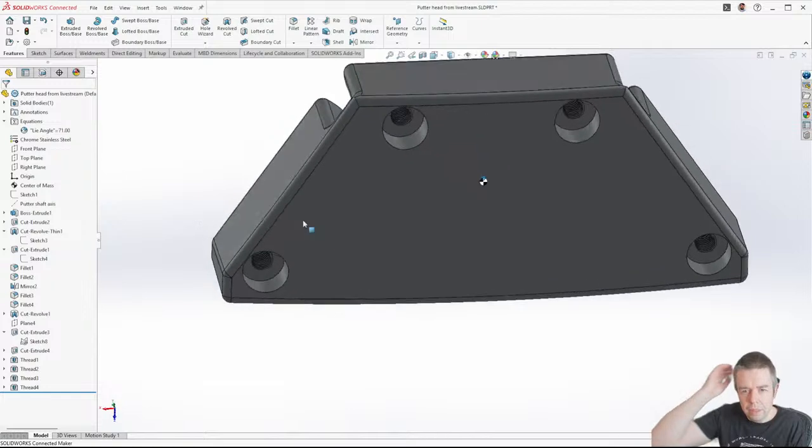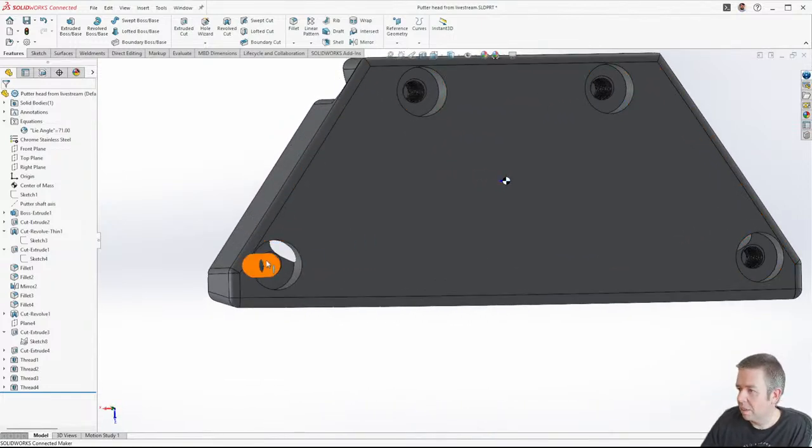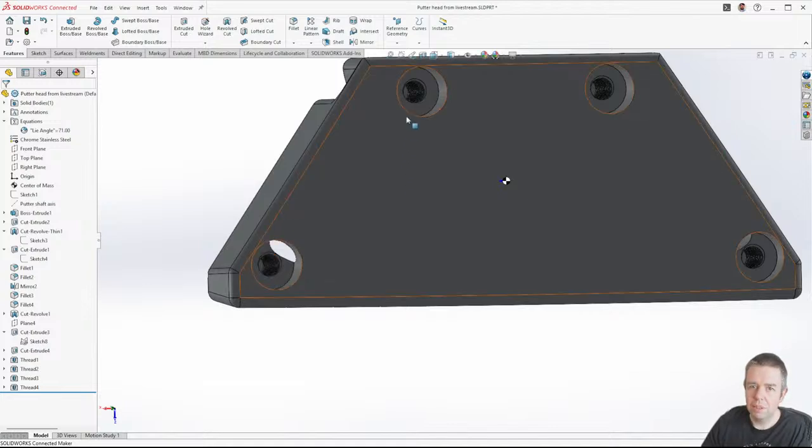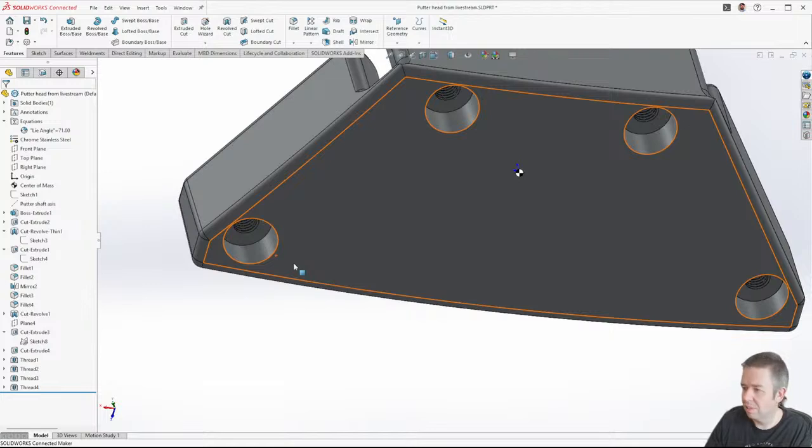So yeah, the idea is we'll put screws in there to rebalance it if we need to after manufacturing, and we can use those holes as locators for a fixture block for an operation, and we can use those threads to secure the workpiece for an operation.